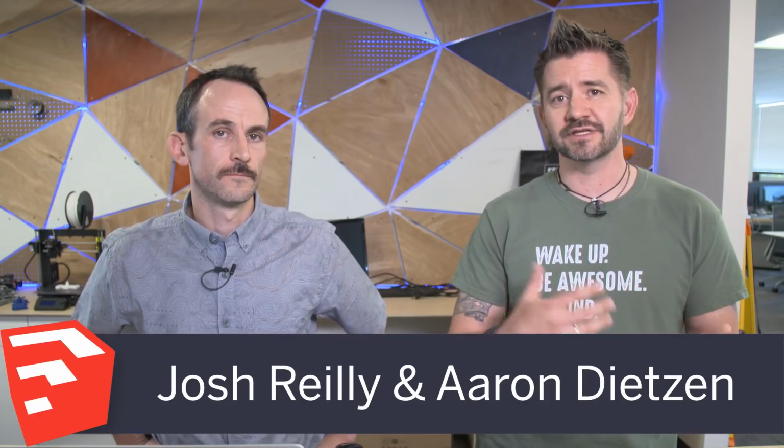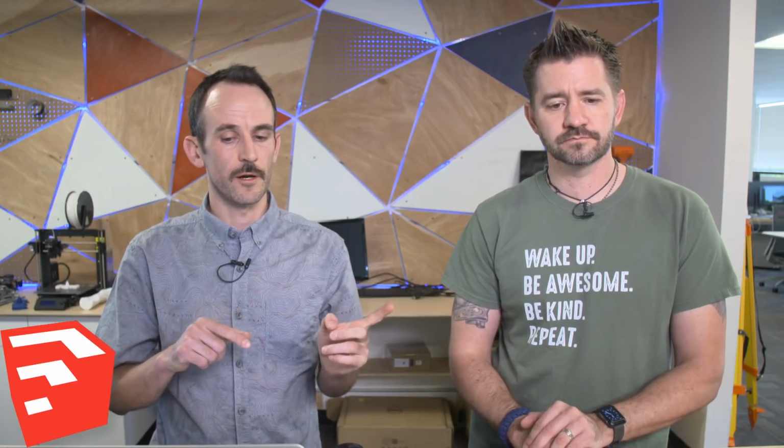Thanks, Trevor. What extensions do people use for terrain modeling besides From Contours, Soap Bubble or Topo Shaper? Those are the big ones that I would say. Really, one of the big things is the data that's imported. A lot of people don't model geometry totally from scratch. They're working off of some other information. So the question comes down to how you get that data in. Do you import a TIN? Do you import a CAD file like Josh was saying? Most of those files are just geometry you import and build from there. And that's where something like Topo Shaper or From Contours comes into play: generating the mesh based on the line information that's imported.